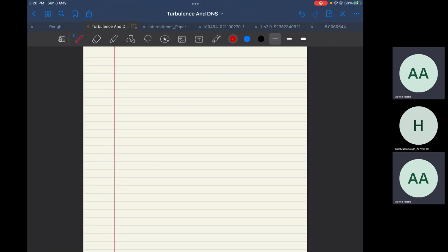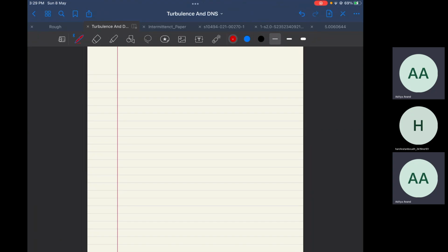We have talked about coherent structures, right? I told you that these are basically eddying motions, or any extended region in space where we will find significant correlation between quantities like velocities or temperature. So in an Eulerian framework, if you have a region of correlation, then that is a coherent structure. Like streaks: these were spatial regions where the velocities were low.